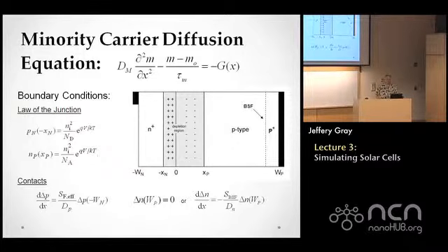And a simple way to apply the minority carrier diffusion equation is to solve it in these regions independently. So we would solve the minority carrier diffusion equation in the emitter region here. And a couple of minutes ago, I had mentioned that you'd see some lateral current flow. And actually let me just digress a moment to talk about that. You're going to have current flowing out of the P side of the device, and so current will be flowing in this direction. The black here represents the contact, so the current will flow in through the contact, and then it'll spread out laterally and flow pretty much uniformly, especially by the time it gets to the base region as it exits the base contact.